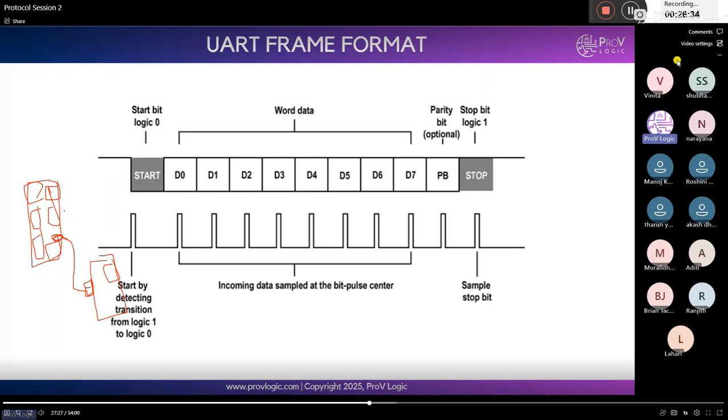This processor interconnect will communicate through here, and through the interconnect to here. This interconnect will be at the processor side. We use a high speed interconnect called AXI. At the peripheral side, we use APB, a low speed interconnect. Between high speed and low speed, how do we connect? A bridge will be there, an AHB to APB bridge or AXI to APB bridge.